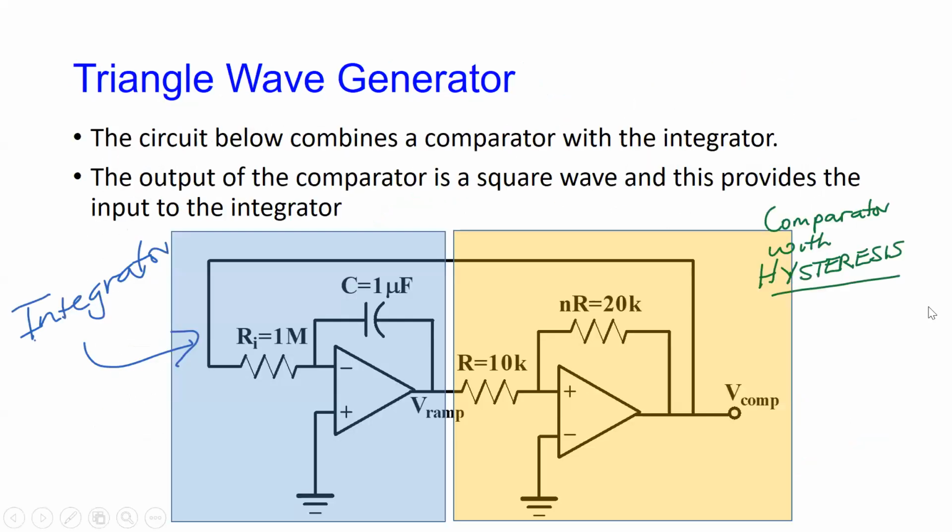So if you combine a square wave generator, which is this character here, with the integrator, then this is producing the steps changing positive and negative, and this one is just simply integrating. So every time the step goes positive, you get a ramp. Every time it goes negative, you get another one, and so it's going. Not drawn to scale, of course.